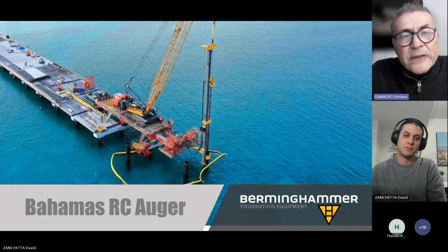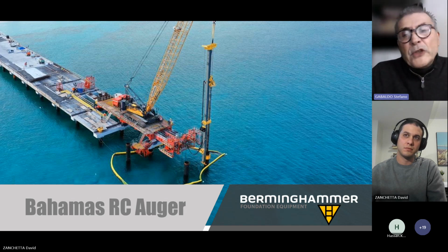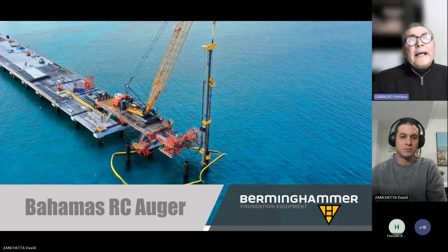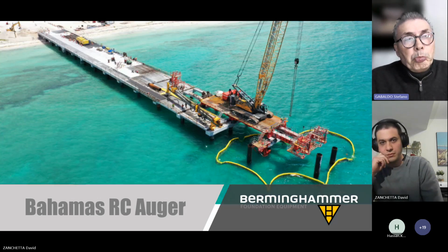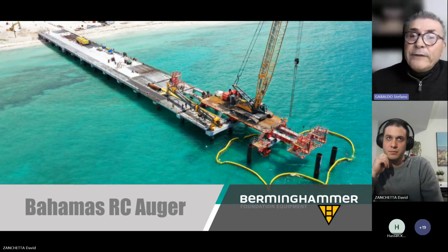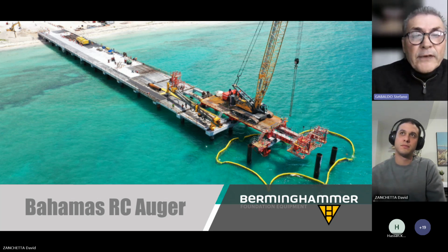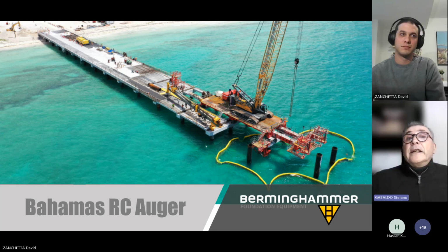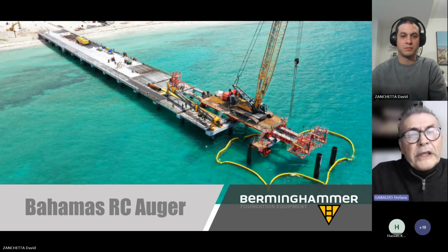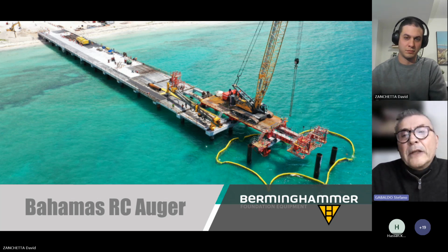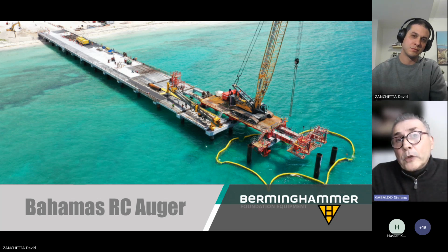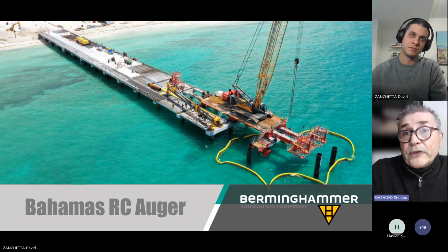This system ended up being twice as productive as your typical marine equipment that you find on barges. And it basically allows the crane to do both the drilling equipment and, when finished, laying down the lead, like it shows in this slide, and perform all the superstructure construction. So basically lay the reinforcing steel, pump the concrete, and all the different placing the pile top cups. So all of this is allowed because now the lead, the crane is just a lifting crane.